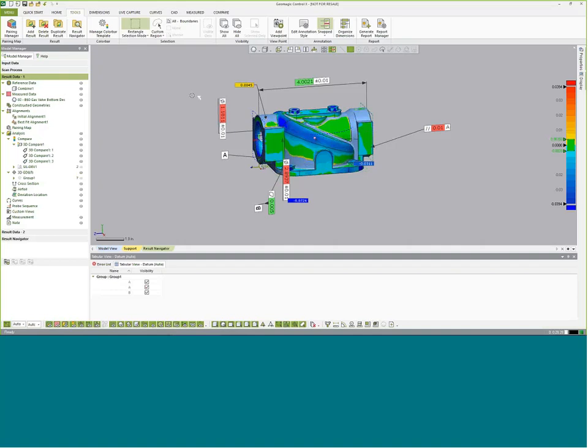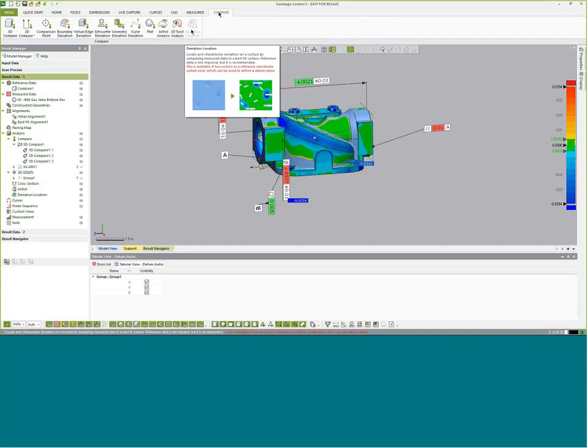There's one more feature I wanted to talk about before we move on here, which we added into CX, a feature called deviation location. We found a lot of users in the past were trying to find things like dents, dings, and holes in parts on surfaces, especially in aerospace and automotive, for their own qualifications. So with just scan data, we can scan that surface in, create a mesh of that surface, and then best fit a NURB surface to that